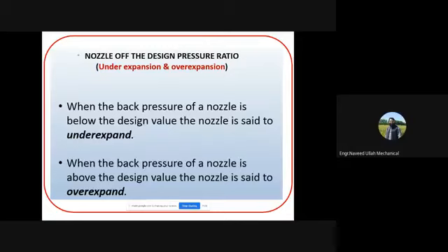And also the pressure at exit. In the convergent nozzle, the exit pressure and critical pressure are the same if they are equal to the back pressure. In the previous slides, we had a duct and a nozzle, and you can control the back pressure using a valve.